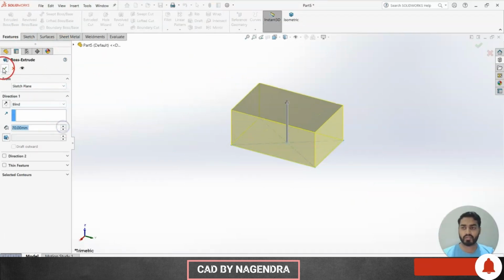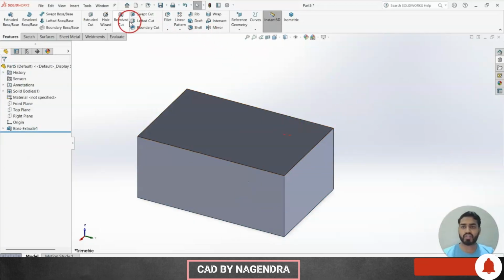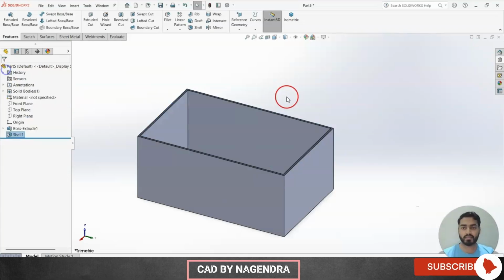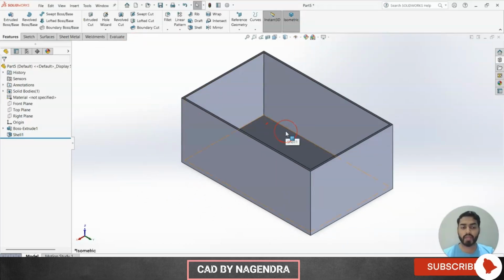I'll make this extrude. Then I'll go for the shell option directly. So I'll go for shell for this top face. For example, I want a thickness of 2 mm like this. Means here also 2 mm, here also 2 mm. All of it is 2 mm, where we have created it in part design.